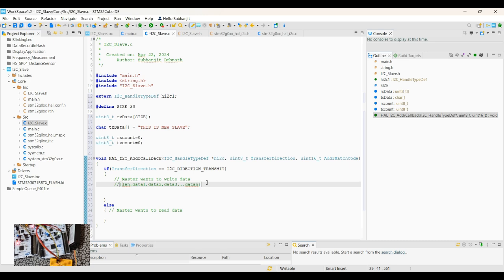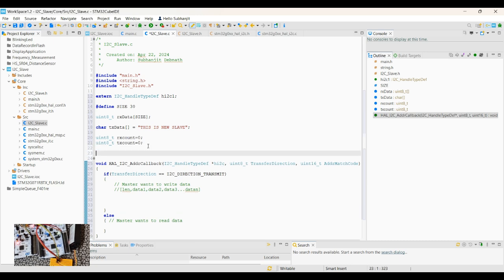Okay, so I will tell you in the upcoming video what acknowledgement failure means. So let's first say that the first byte should be sending the total number of data that the slave is going to receive. Okay, so first we need to check if this is the first time the data is being received. So for that, let's create another variable, uint8_t first_data. So first_data I am making it 0.